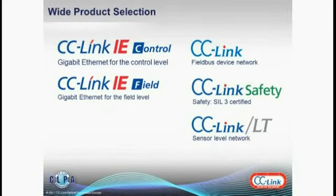Then on the right side, we have the field bus networks, which CC-Link also offers. We have CC-Link itself, an RS485 based field bus. We have CC-Link Safety, which is a similar technology but intended for safety applications. So it's SIL 3 certified for safety critical applications. And then finally, we have CC-Link LT, which is a lower level bit bus type of network, which is intended for the economical connection of simple digital devices.